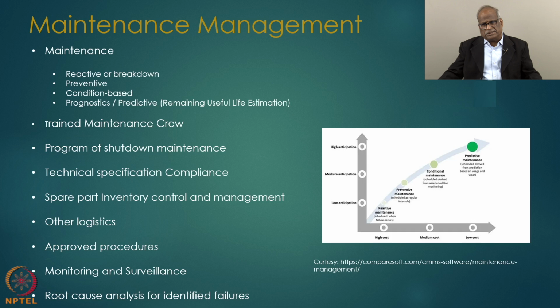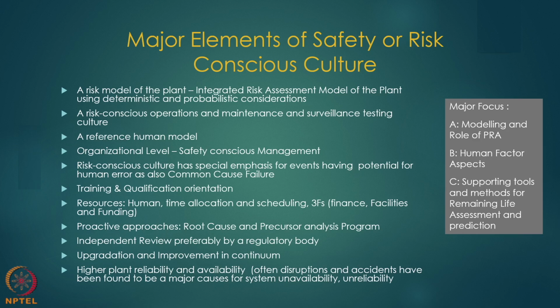And of course, root cause analysis. It is to say that this is one of the most important areas. RCA, that means root cause analysis, is being performed, and it forms part of operation, design, and maintenance. But getting to the root of it is very important. How will you know whether you have gone to the root of it? If you are not going to the root of it, the failure might recur, maybe at lesser frequency, but it will recur. But if you have done exact, good root cause analysis, the failure frequency will reduce to a great deal.